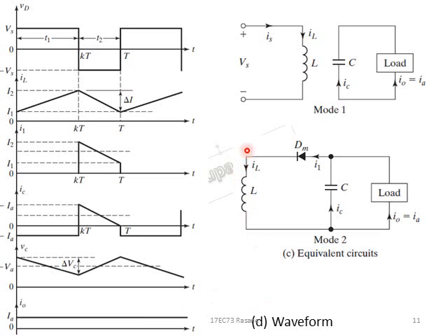Now, when the current through the inductor is flowing, in mode 1 the polarity was plus minus. When the switch opens, the property of the inductor is to reverse its polarity, minus plus. Earlier we were assuming the load voltage to be 0 when there is no connection, but during this time the load voltage will be negative.